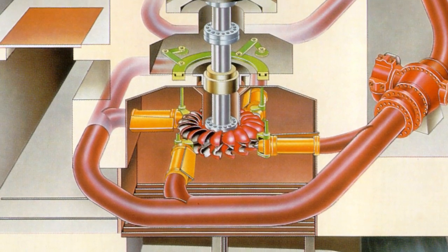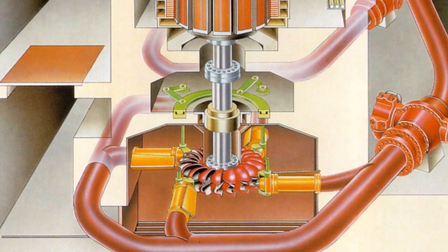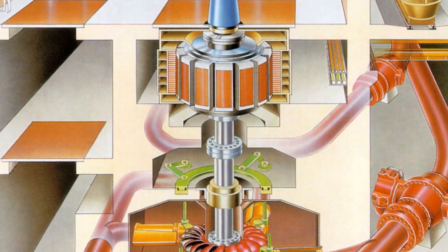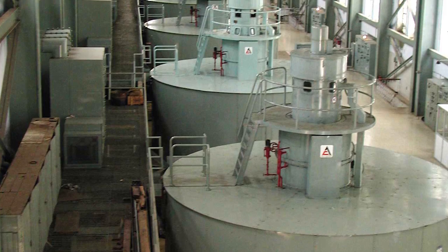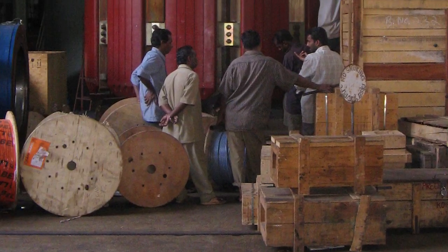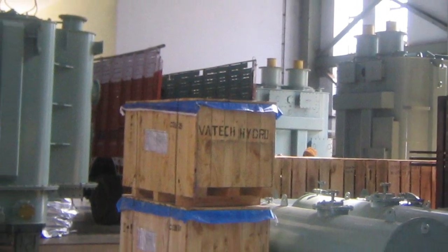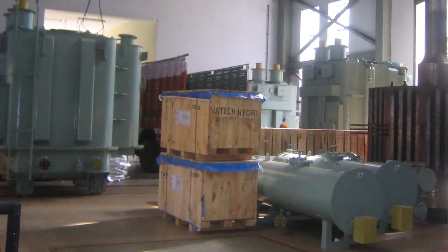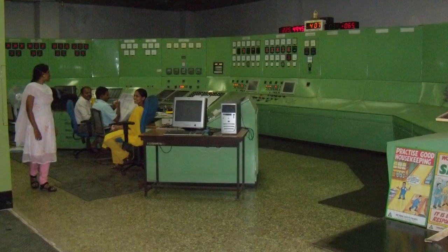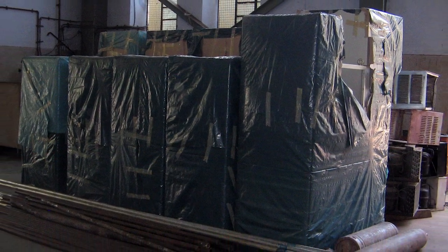The layout of a powerhouse consists of various floor levels like erection bay, service bay, machine hall, generator floor, turbine floor, etc. Erection bay is an area provided for the assembly and disassembly of major generating components. Service areas include offices, control and testing room, storage room, etc.